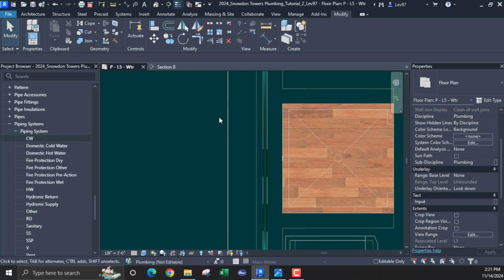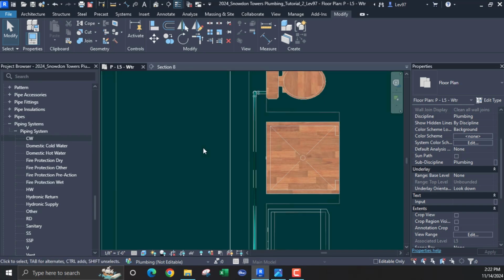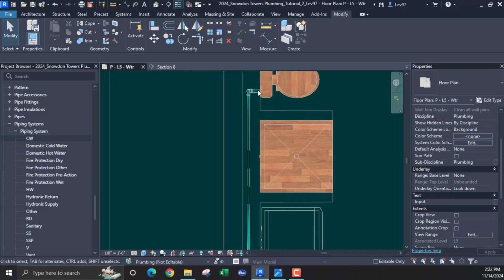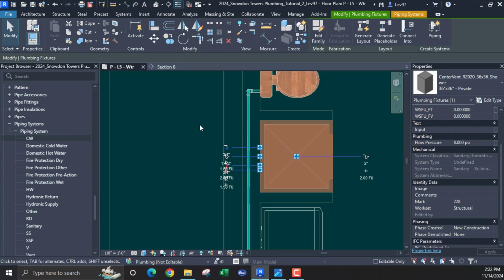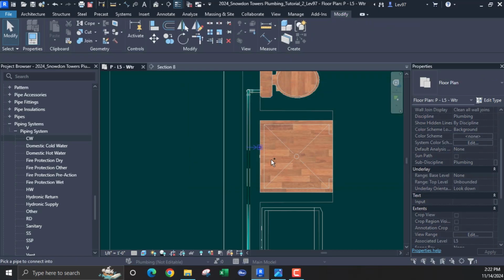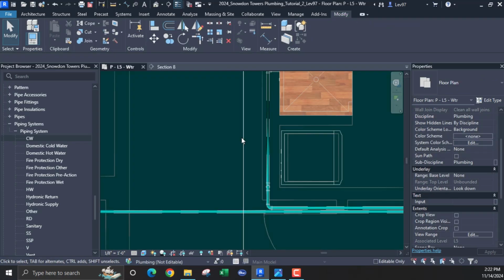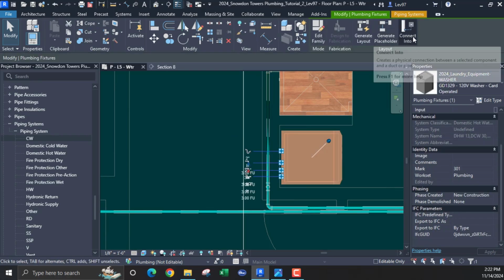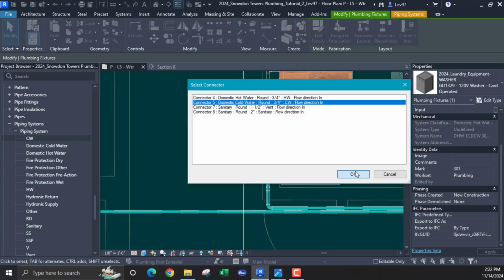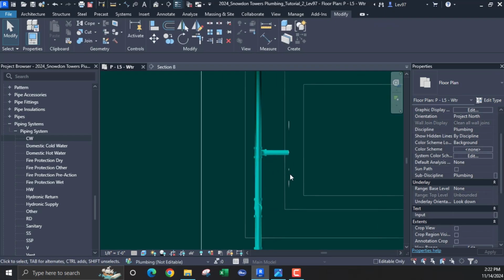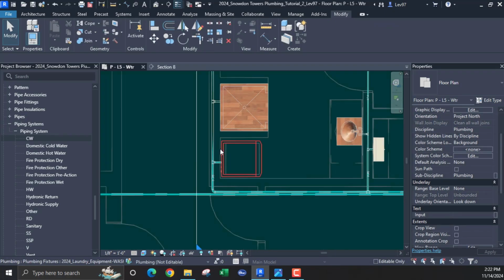So it should be easy, because a lot of times when you connect into, Revit's pipe will overlap and it'll go all the way to the end and then come back. So I like to tie in both ends so that Revit doesn't go all the way to the end. That way I give it no options. Let's connect into cold water. Yes, and we are here. Has no choice. Connect into cold water, and we are here. Okay, so that looks good. We have that. Let's sync again.